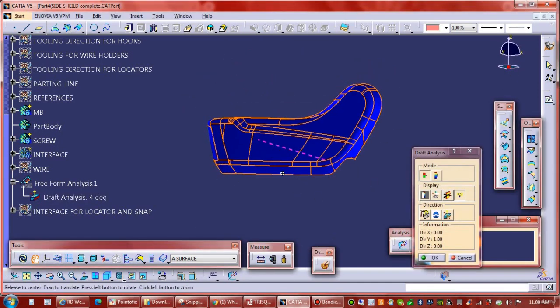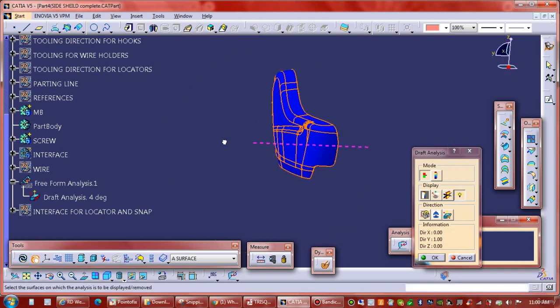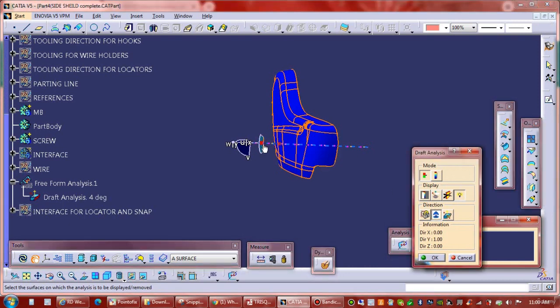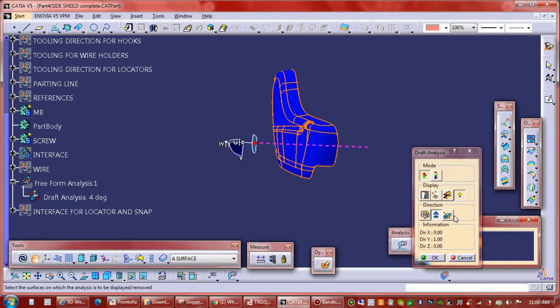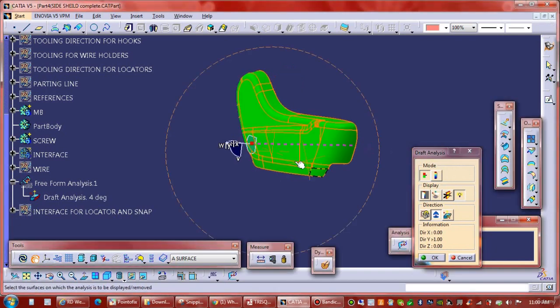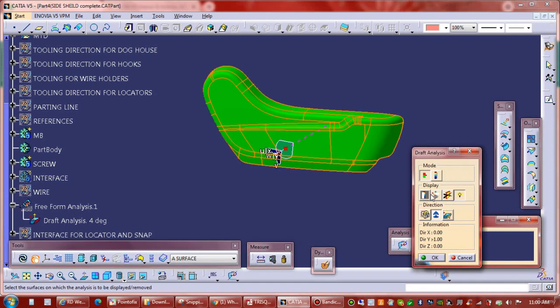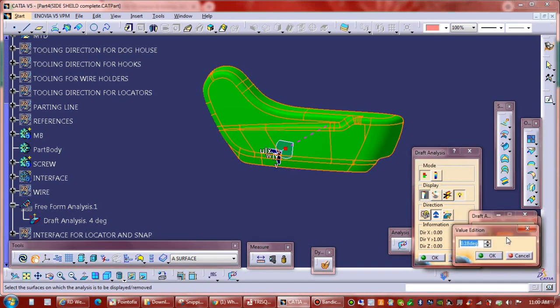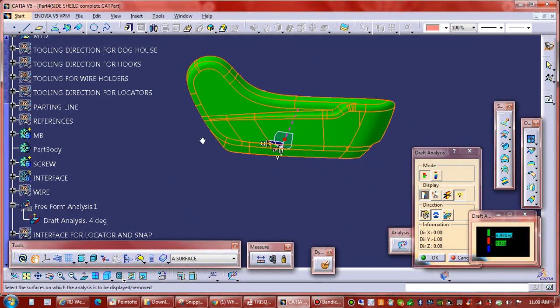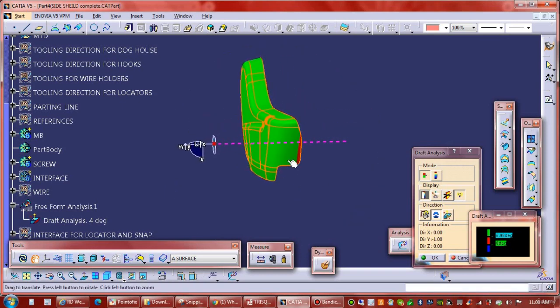This is our analysis menu. Basically we check cover all plastic for 7 degree from main tooling. Here I'm checking this at 6.98, which means 7 degree. You can see this is looking blue; only two colors will come. The color code is given here, you can check what the meaning is.